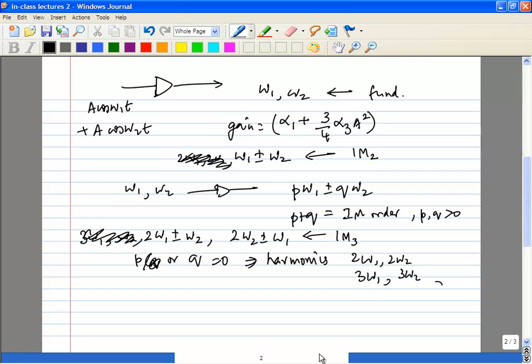Second reason is, in a real case, you would have multiple signals in a very small bandwidth. I gave the example last week: if somebody is receiving a call, and somebody else is transmitting something very close by, you could have a very large signal right next to it. So you want to be able to characterize such a situation. That's the reason why you want to do it in terms of IIP3 specifically.